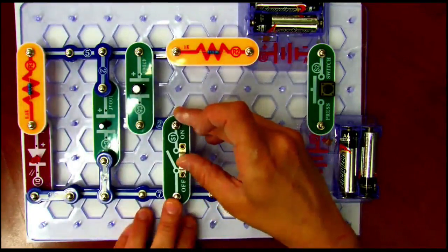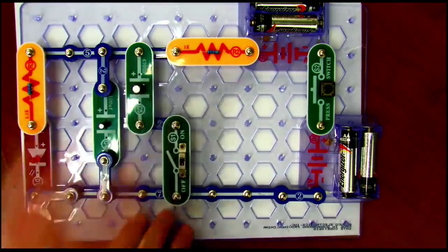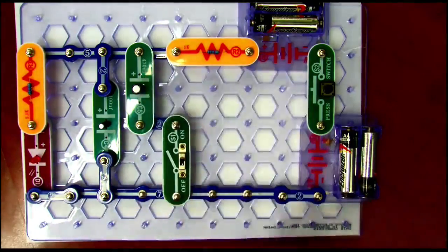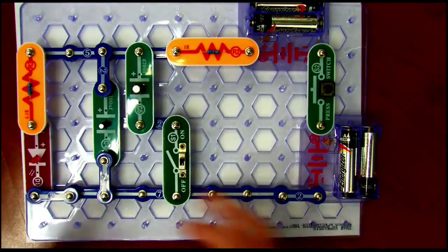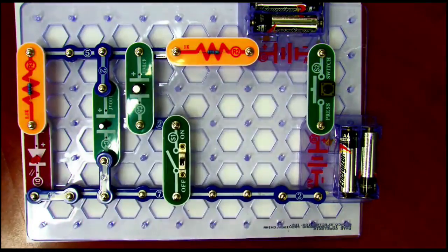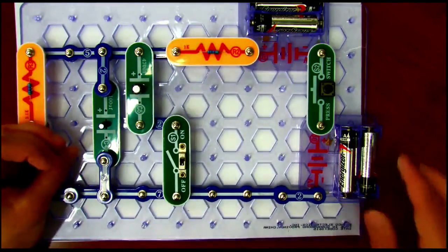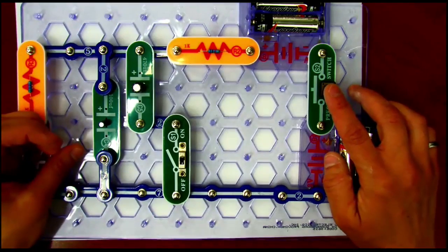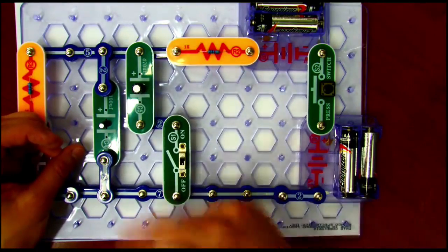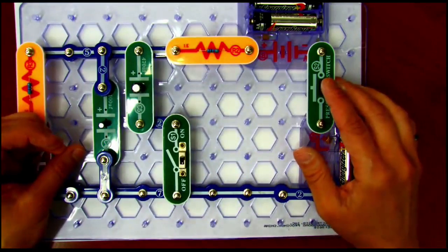But these two are in parallel. I'm going to turn this switch on. So these are both now parallel capacitors. Parallel, you straight add. So 470 microfarads plus 100 microfarads. We're going to have more energy stored in the electric fields inside these little capacitors to use for the light bulb. So while they're discharging, it should last longer than it did when just the 100 microfarad one was there.